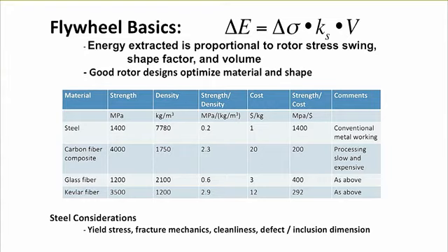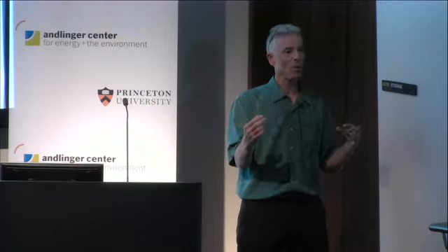So, maybe this is a little bit superficial, but it begins to explain. Maybe replace strength as a sort of placeholder number with something like a life cycle rated strength. So if one sets out for 20,000 cycles, what is the usable stress in the component? That would define that basic function for the rotor. And in terms of how much power, there's probably a real limit where things get to be on the hairy edge, but we're so far from that.